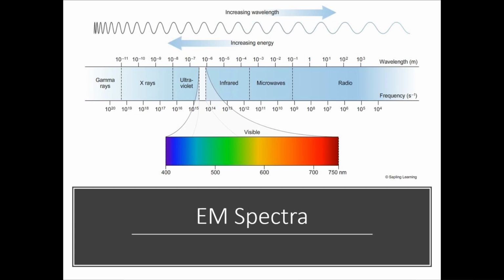Yeah. Then coming to the next portion of the spectrum of interest is the infrared radiation region. It covers from about 0.7 to 100 micrometers. So you can see that it is about 100 times as wide as the visible portion, right? This is basically divided into two categories. One is the reflected infrared and another one is the emitted or thermal infrared. Radiation in the reflected infrared region is used for remote sensing purposes similar to that of the visible portion. And the thermal IR region is pretty different, which is of longer wavelengths.